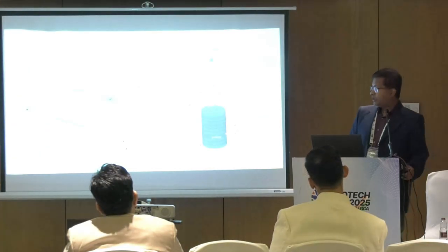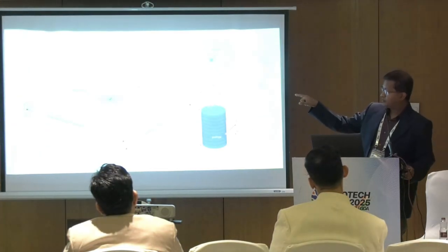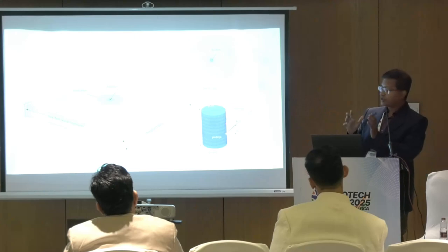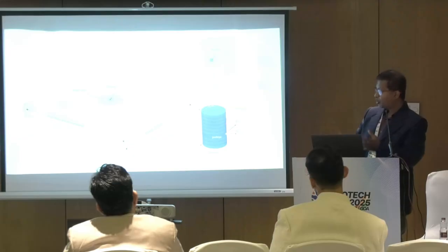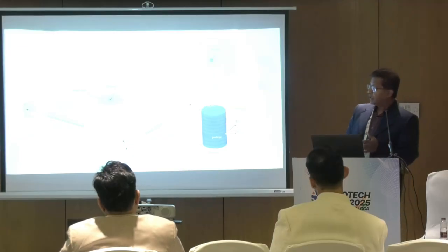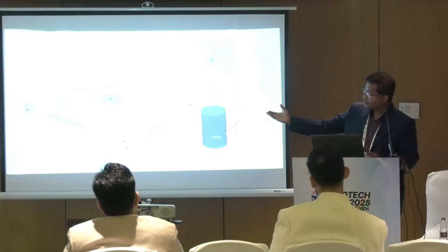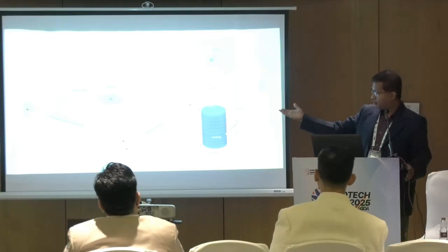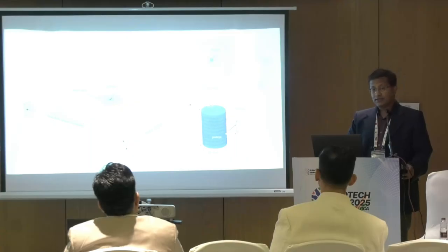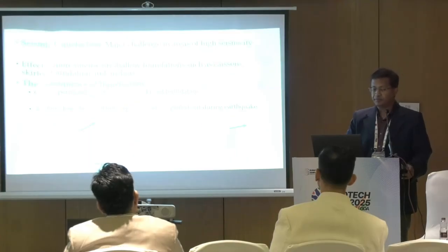So this is a typical model that has been adopted, that means a three-dimensional continuous anchoring system and the overall system. It is a complete modeling system we have done. And then for seismic analysis, we can apply the seismic loading at the base as a compliant base, and we can see the overall behavior of the system.